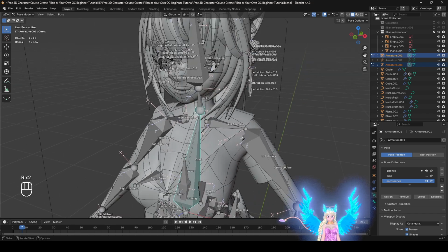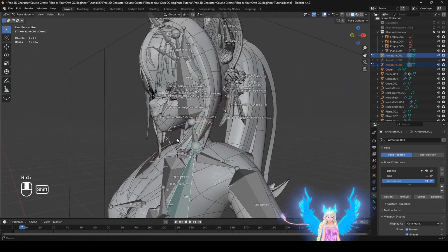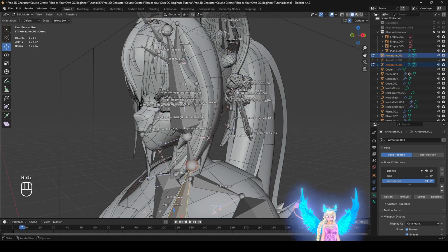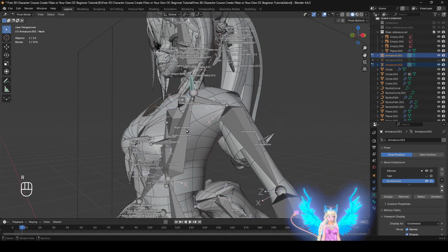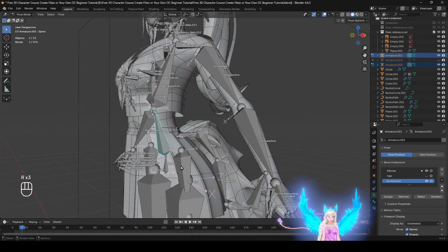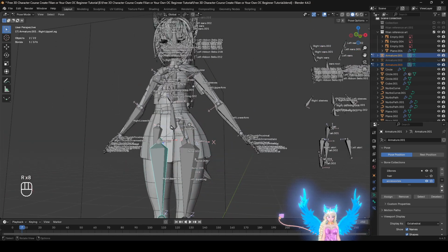All right, see how the head doesn't connect? All right, that means we made a mistake. So go back right here. Click right here, hold down Control, left click right here, Control P, connect. All right, so now when we go into it, it's all connected, see? I know, sometimes it happens if you press a button and accidentally did something really dumb. Okay, good, see these are connected.